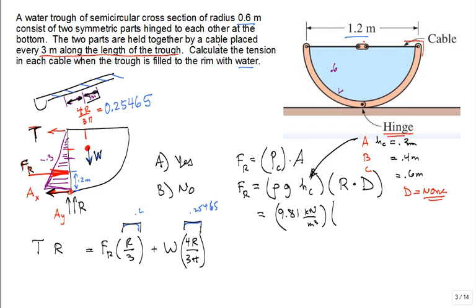All right, so why is it 0.3? It's not the centroid of the triangular pressure distribution. It's the centroid of the area in which the water is pushing against. And that water pushes against what looks like a rectangular area of 0.6 and 3 meters. And so you put the centroid, it's 0.3 down. 0.3 down. The answer was A.